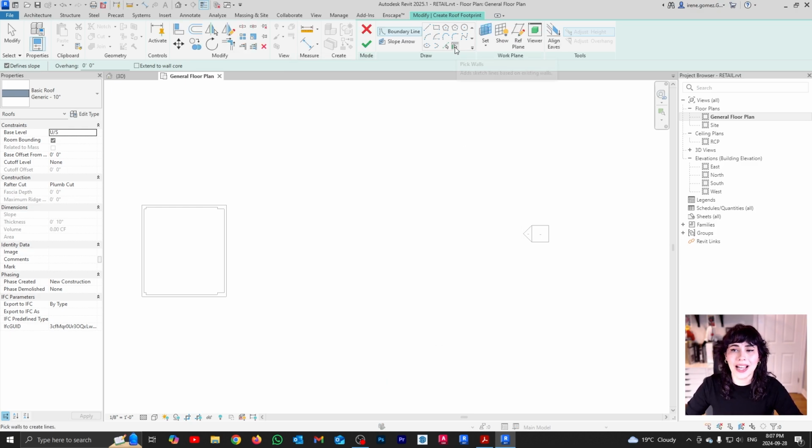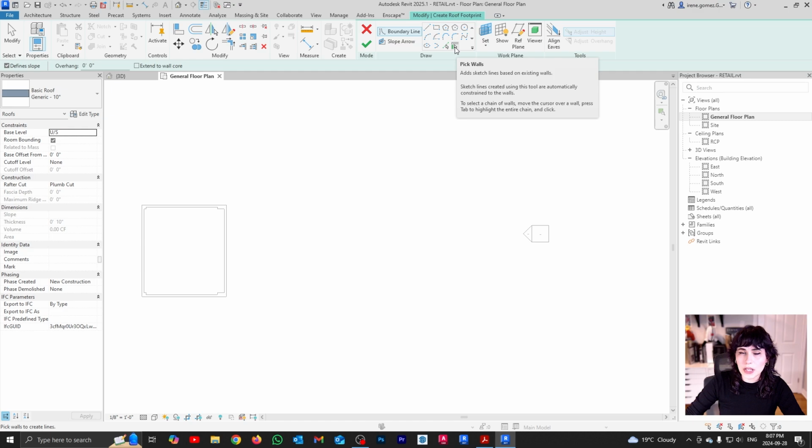Same as with my floor, I have the option of choosing big walls, and basically I will treat my roof the same way that I treated my floor. That means that I would put the boundary of my roof at the outer side of my perimeter walls. It's exactly the same reasoning as when we were drawing the floor. Remember, you are taking a slice of a bigger pie. So basically we want all of our elements to end where our walls end.